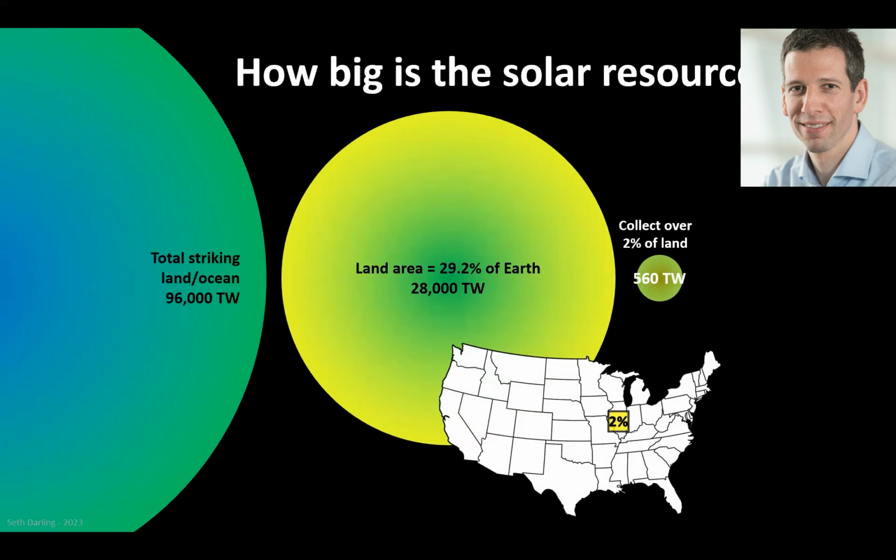Feasible. But there's another problem, which is that solar panels don't convert sunlight to electricity with 100% efficiency. There are fundamental limits in that process. Thermodynamics limits you to roughly 30%. It'd be much more conservative than that. You can buy a solar panel for your roof today, maybe some that's commercially available today. I'm going to be much more conservative. I'm going to say 12%. Very realistic number to achieve as a global average for conversion efficiency. So you can see we're down to a pretty minuscule fraction of that monster circle that we started with.